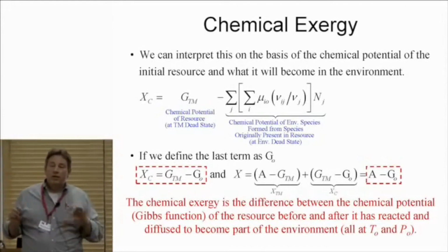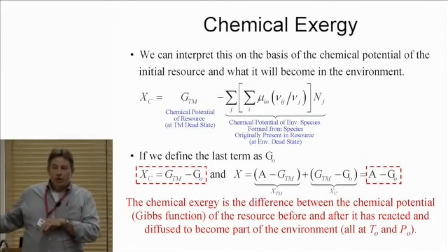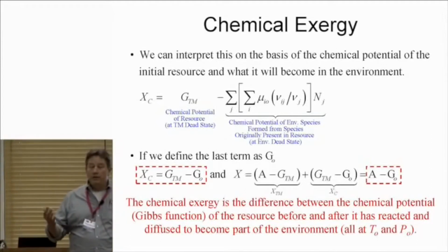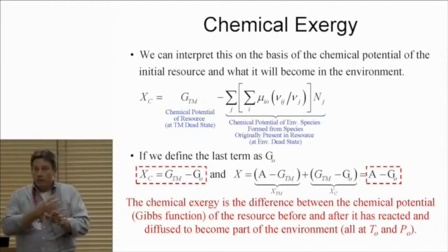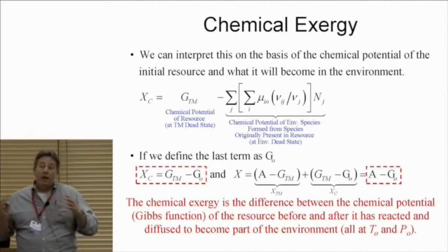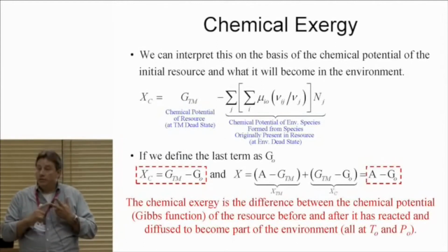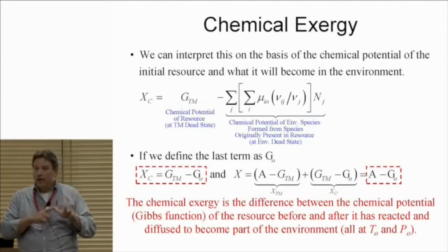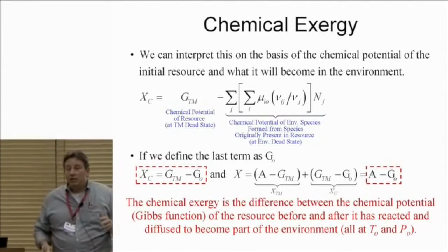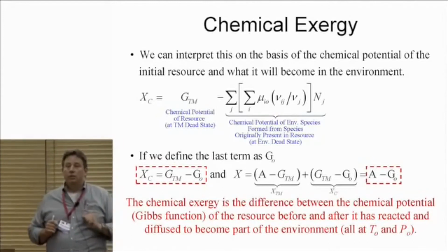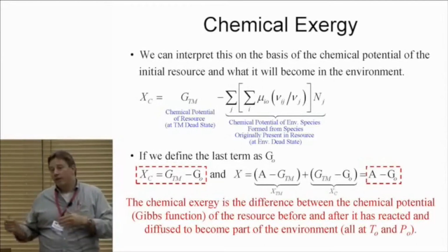Exergy, for those of you who know free energy, exergy is environmental free energy. Gibbs function is the work you can get from a chemical system reacting at fixed T and P, but no transport reactions, no transfers across. Helmholtz free energy, fixed T and V. They're not the only two. If I hold S and V constant, the internal energy is a free energy. If I hold S and P constant, enthalpy becomes a free energy. If you tell me that you can make a path where PV to the K equals 17, I can define a free energy for that too. Exergy is literally environmental free energy.